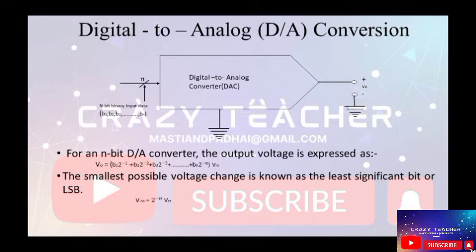Then based on these values that we have got, if all these bits B1, B2, up to Bn are zeros, then what you get is 0 at the output. So if you are giving all 0 here, you are getting a 0 output here. On the other hand, if you are giving all these bits as 1, then the expression VO will be very close to VFS.